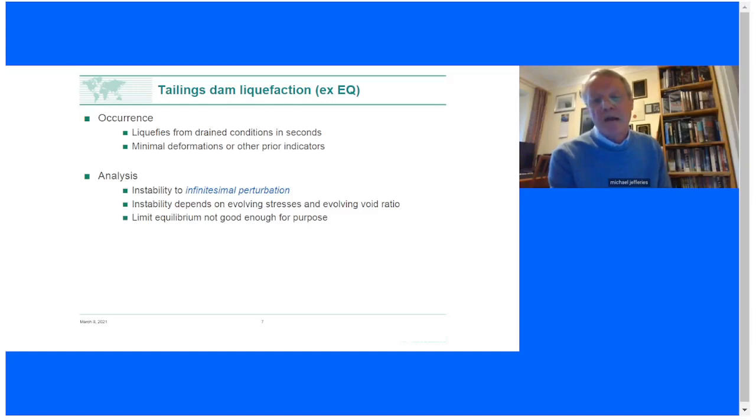The vibration from that was sufficient to trigger the liquefaction. Now, the kicker is that the sensitivity to this perturbation depends on stress state and it depends on void ratio. And both of those are evolving as we build the dams and we stack the tailings behind them.